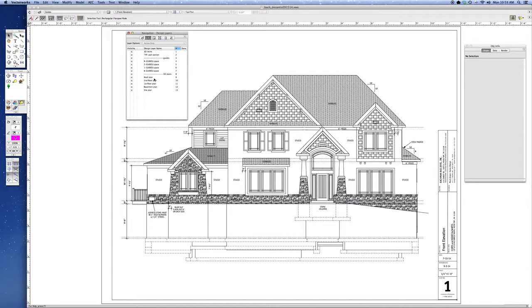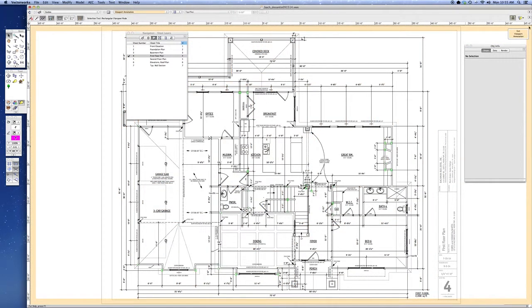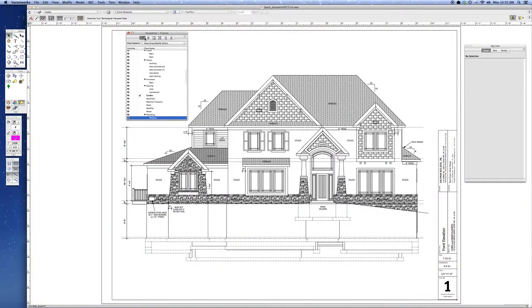All of these design layers will already have their Z height preloaded, so that you shouldn't have to worry about changing the Z height. I'll already do that for you. Any 2D items like notes and dimensions, those kinds of things, I always put those on the, let me just show you, save sheet layer. First floor plan, those are always just in the annotations, so that's where I keep those. These 2 layers are just visual dividers to divide up the different kinds of layers that I have here.